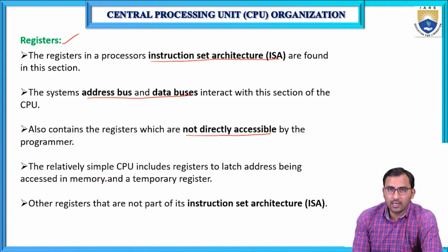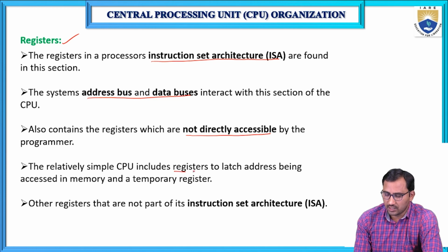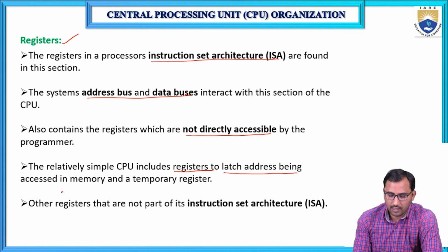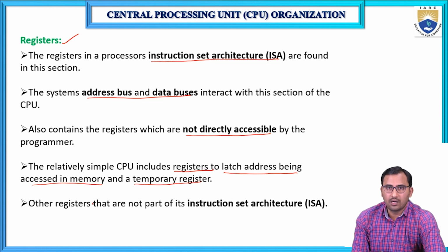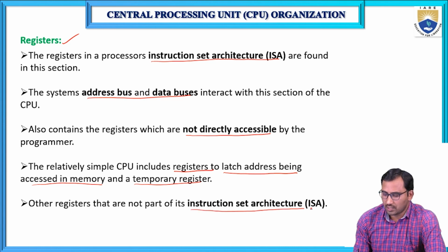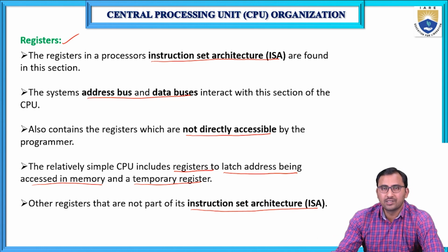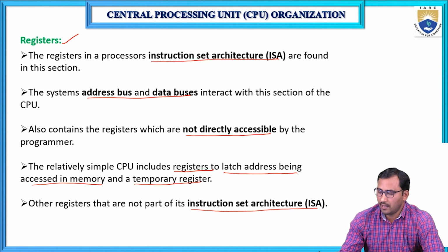And a relatively simple CPU includes registers to latch the address being accessed in memory and a temporary register. The other registers that are not part of the instruction set architecture are also contained in the register section. So that means the register section contains the registers of the instruction set architecture, and also the registers which are not related to the ISA.